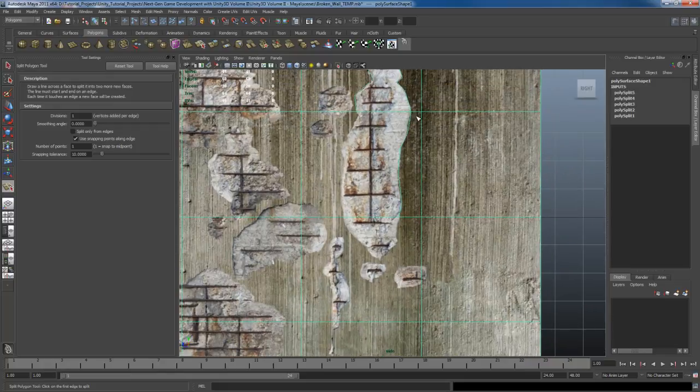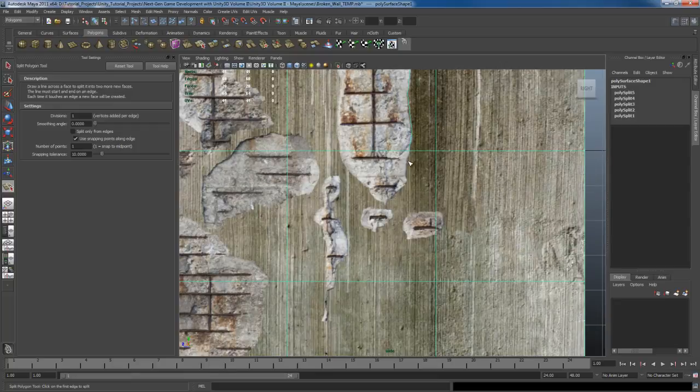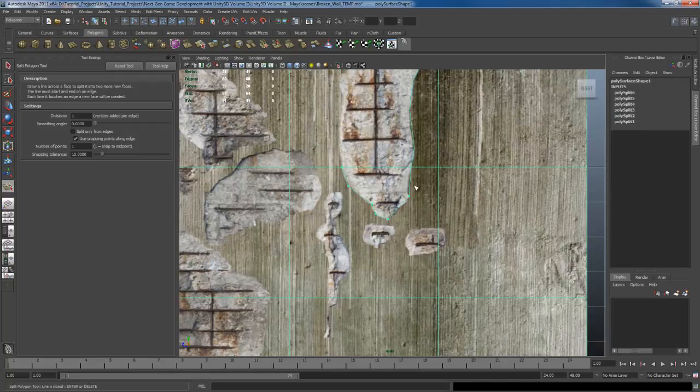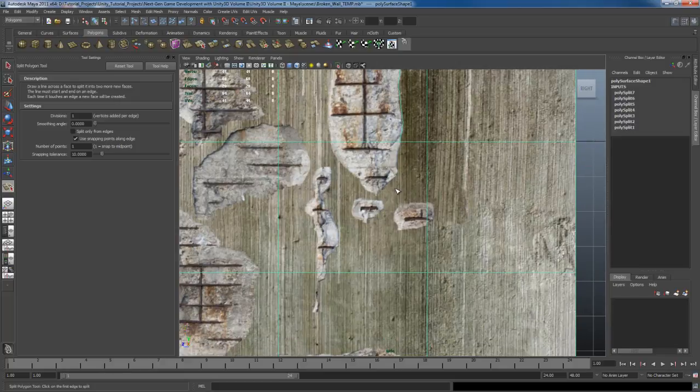See right there? This whole split was created, but then the split right here didn't work. That's because Maya doesn't like it when you create a split that doesn't triangulate properly. Maya will simply reject it, and it can be kind of frustrating if you don't understand what's happening. So look at how I did this split, and if I right click to end it, it's going to delete it. If you don't know what you're doing and you're new to this, it may end up frustrating you.